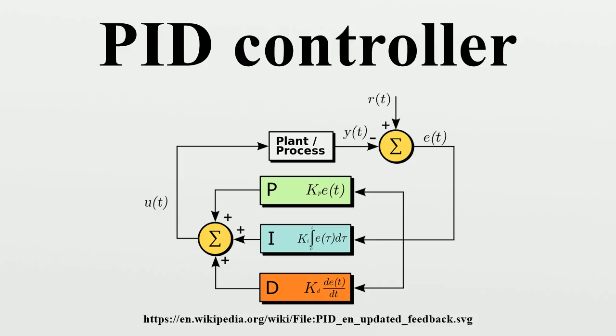The sensed position is the process variable. The desired position is called the setpoint. The input to the process is the output from the PID controller. It is called either the manipulated variable or the control variable. The difference between the present position and the setpoint is the error, which quantifies whether the arm is too low or too high and by how much.